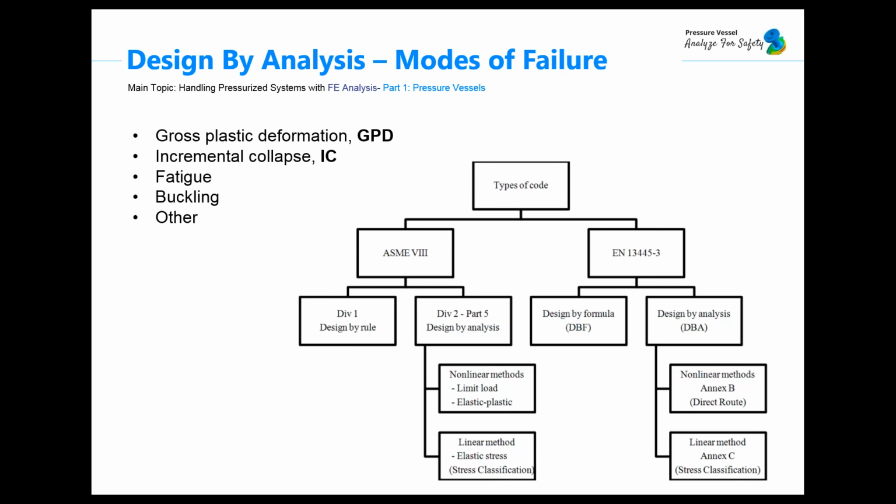So, for example, there are cases when the loadings and geometries are such that the procedure cannot be applied effectively, and this happens when designs are very complex. It's not possible to provide equations for these areas. For example, if there are a lot of nozzles or other discontinuities, it becomes difficult to apply this approach without a big margin of safety. So this solution is sometimes not economical for complex designs.